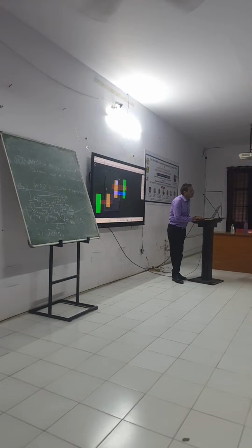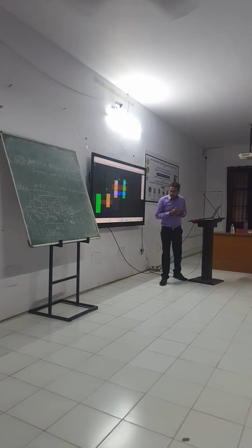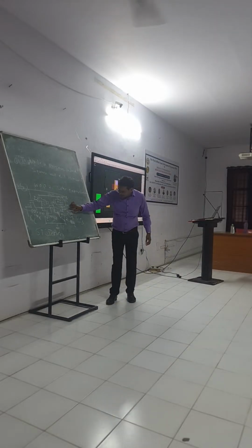Here again we have to give a ground terminal, so you can give a metal contact here. Its name you can apply here as ground. So here it will be the ground, G and D. Okay, so this is the ground. So this is one, MP2, MN2 finished.